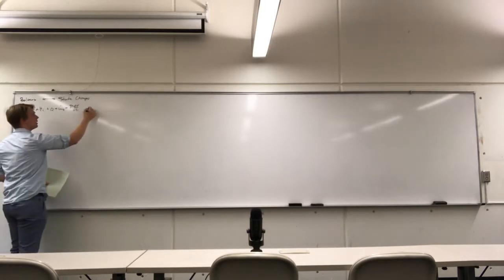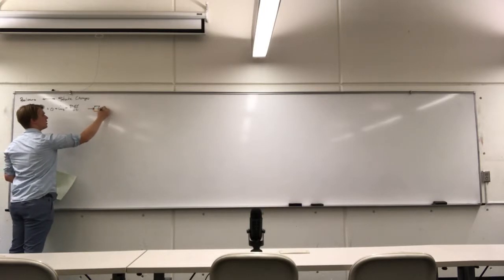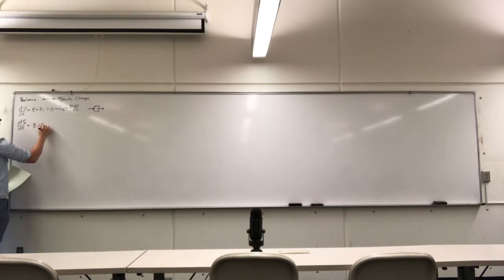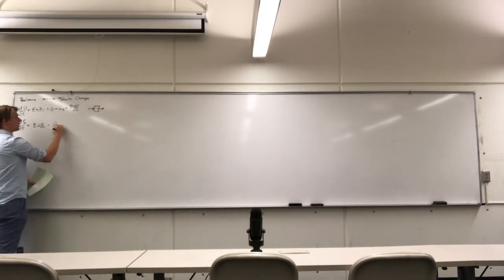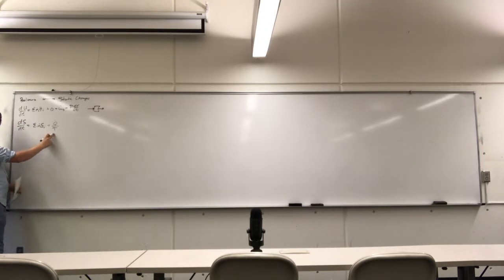So this system here is just any process that we can basically draw a box around, or a loop, or any sort of oddly shaped defined boundary. We also have the entropy balance, where we're adding up all of the entropy flowing into the system or flowing out of the system. Entropy is an extensive property, so mass or moles carry with it entropy. Entropy can flow in and out of the system in the form of heat.